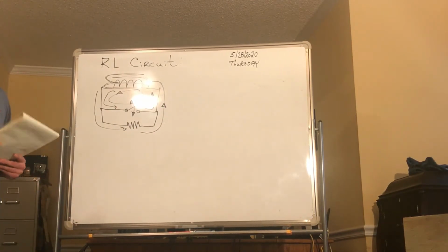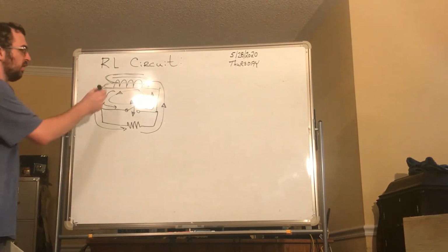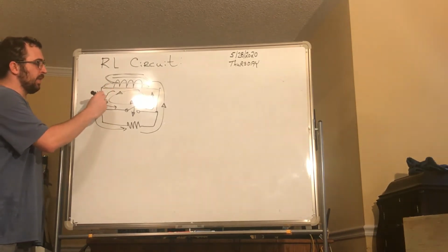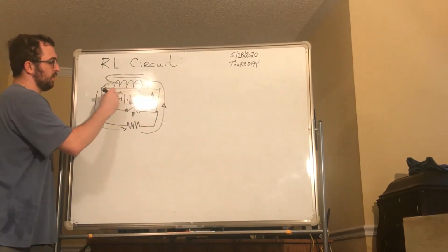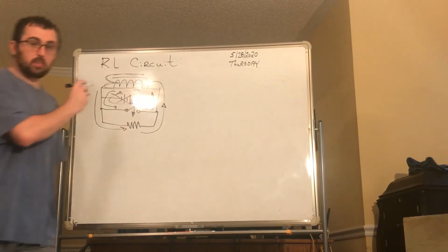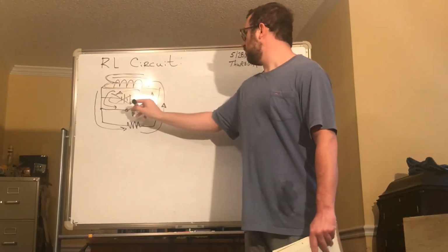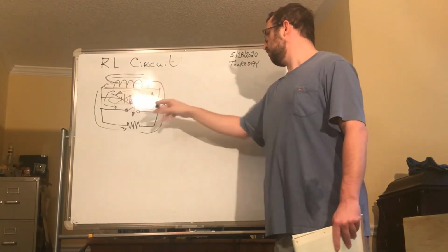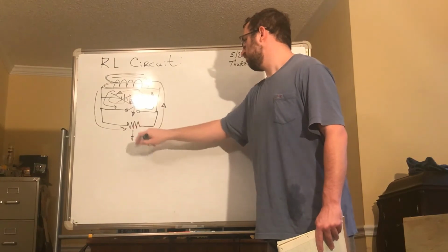It's very similar to the fundamental RC circuit, which I will cover as well. You may wonder how the current could get started, and in practice you would have a battery and a resistance which would start it. But we're going to assume that was removed just before. But let's address the circuit. You have a current flowing through a zero resistance path, and you give it a resistance, opening up the zero resistance path, which means it's going to produce a voltage, and the current will drop because energy is being lost as heat from this resistor.